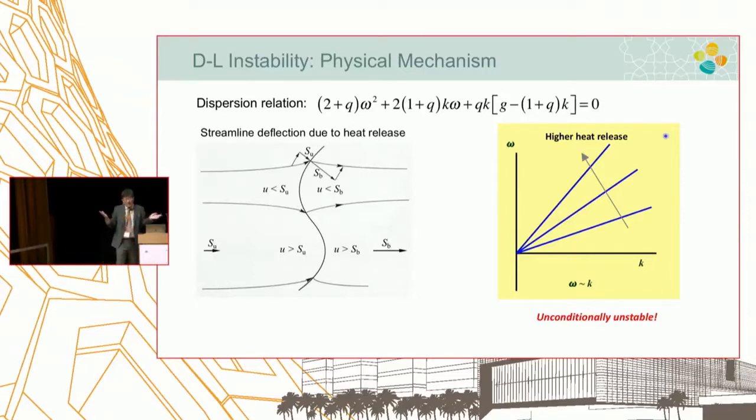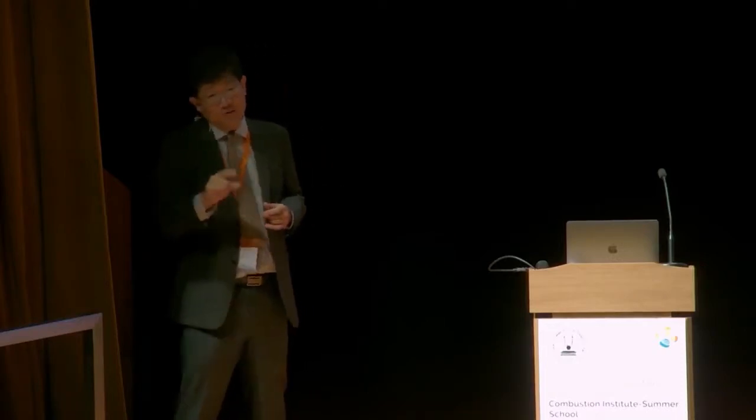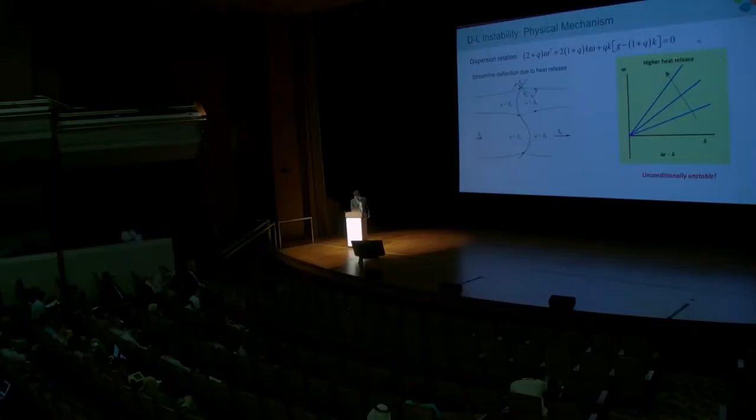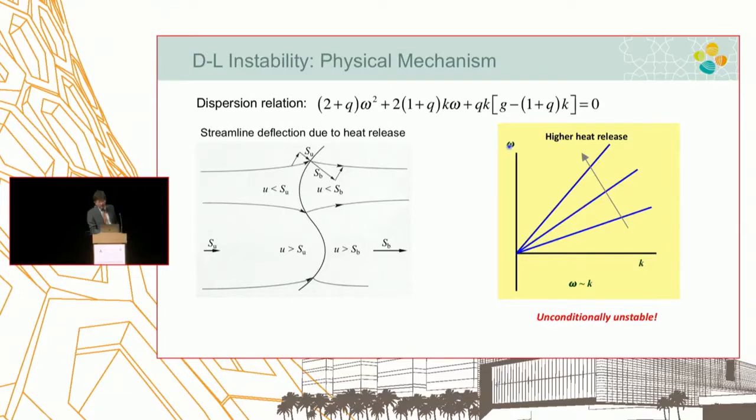But at that point, in today's world, we do numerical simulation. Indeed, if you do DNS of this flame, you will find that the flame will be wrinkled and saturated at a certain amplitude, which is the effect of the nonlinear aspects. Does that answer your question? Yes, thank you. I understand the meaning of omega and k. This is an input, this is a response. If this is positive, unstable; negative, stable.